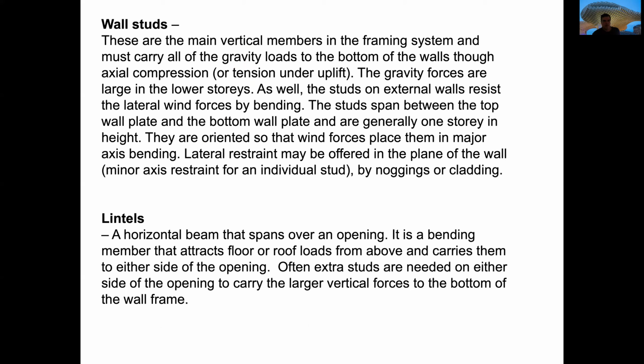Here we have some explanation about what the wall studs are. They are the main vertical members of the framing system, and they carry all the gravity loads to the bottom of the walls through axial compression. They are working in compression. There is tension also, obviously, when there is wind that tends to lift the roof, and therefore the studs that are supporting the roof will tend to have some kind of uplift. The gravity loads are larger in the lower stories. It's obvious because they are also supporting the superior floors.